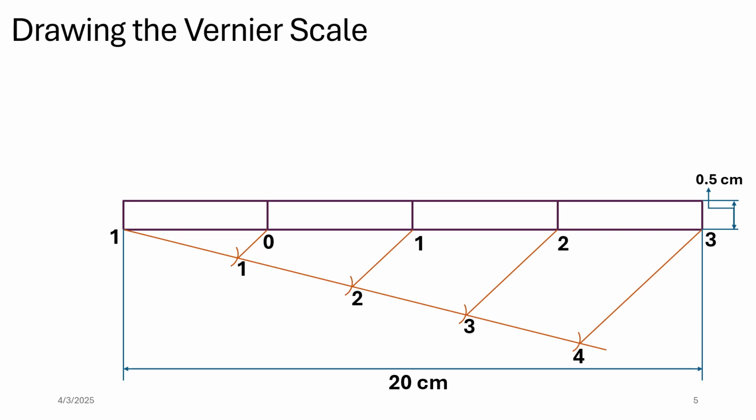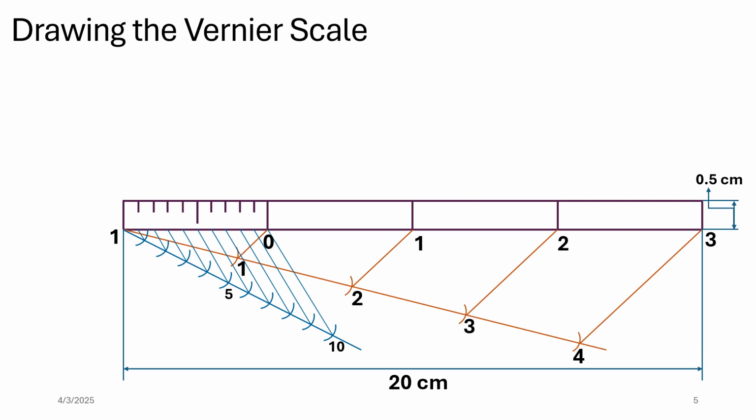So first dividing the first one from 0 to 1 on the left side. So here for this one we take this line, draw 10 arcs of equal radius on this line. So here are our 10 arcs. We join the last one with 0, and then from other points draw lines parallel to the first one. Once it is done, for these points we draw lines from the upper part to coincide with these points. So here is the division of this part.